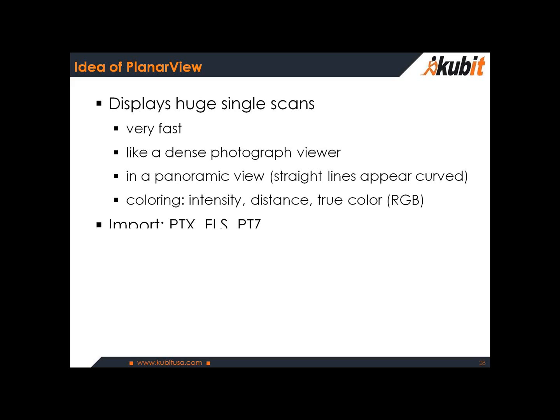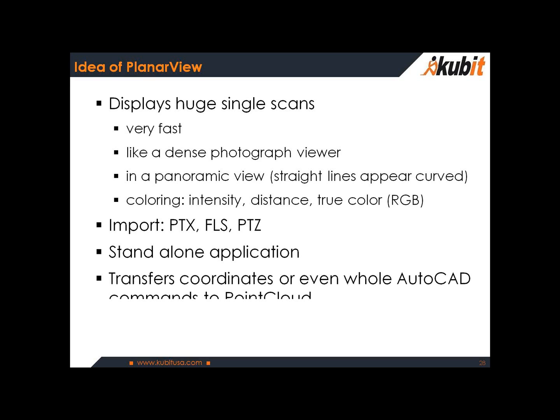You can import PTX, FLS, or PTZ files directly into PlanarView. Now this is a standalone application. It's working outside of AutoCAD, but it will give you the ability to transfer coordinates from this high-quality panoramic view directly into AutoCAD. You can also use entire AutoCAD commands.